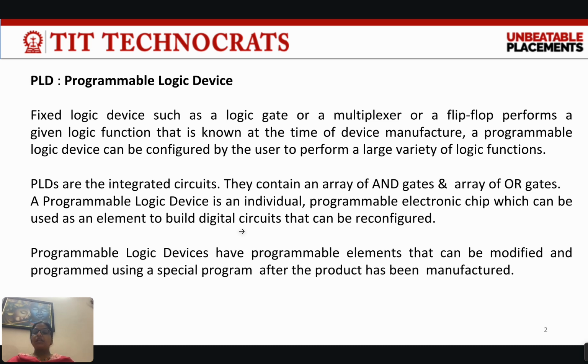So let us understand what is PLD. PLD stands for programmable logic devices. Fixed logic devices such as a logic gate or a multiplexer or a flip-flop perform a given logic function that is known at the time of device manufacture. A programmable logic device can be configured by the user to perform a large variety of logic functions.